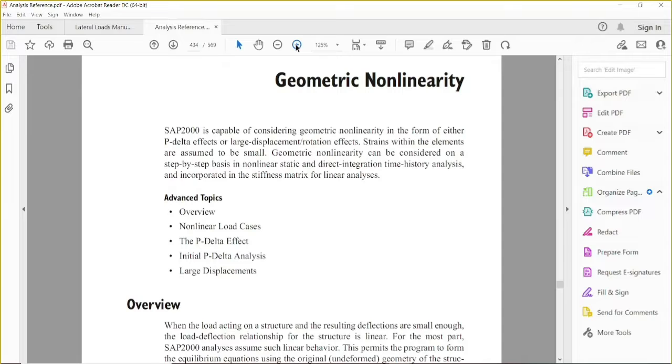When you are constructing any structure with a large height compared to the cross section, what happens if you provide the dead load and live load? The structure deflects due to the self weight and an additional load which is being added laterally. So you have two loads. What are they? One is vertical load due to gravity and the second is horizontal load due to wind or earthquake. So when two forces act simultaneously, what happens?